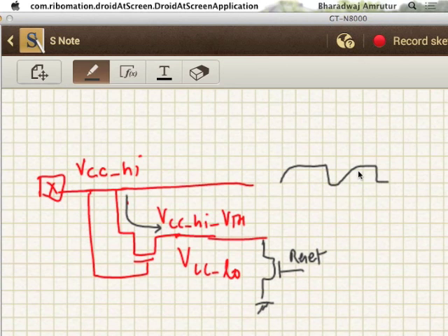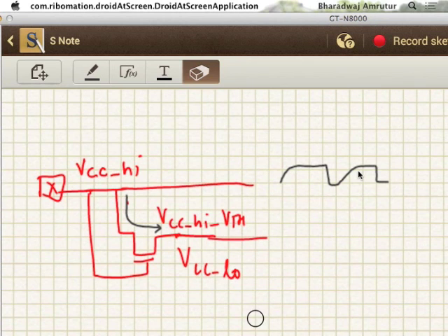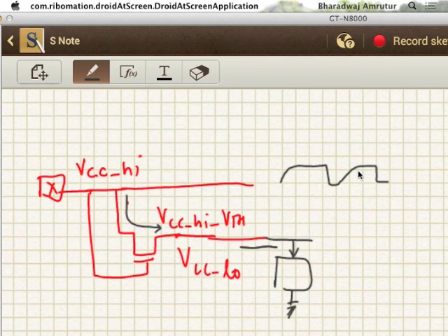That is one problem. The second problem is, if there is some load circuit out here that is drawing a certain current, an ideal power supply should be able to supply any current. A real power supply will have some impedance, right? As soon as you start supplying current, the voltage of the supply starts going down. So how good is the impedance looking into this? This NMOS is almost off, even at VCC minus VTH. So it doesn't have a low enough impedance. So it's not a good supply, and you don't want to use this.